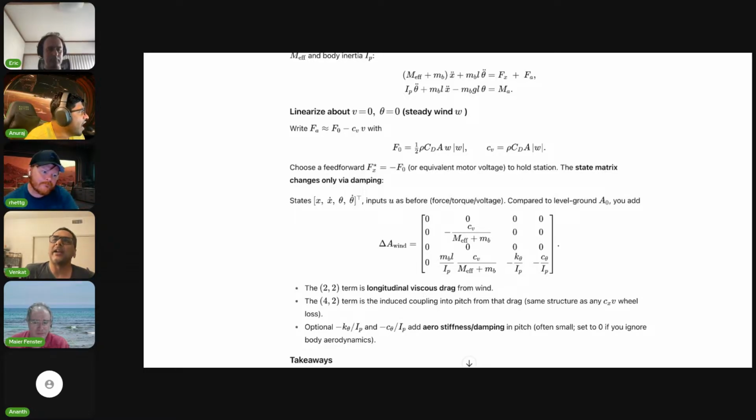If the wind is steady and you have enough control authority, so the actuators do not saturate, steady wind within control limits is basically manageable because you ramp up the integral control term, compensate for it, and push back steadily. Unless the wind is too strong, then you get blown over completely.